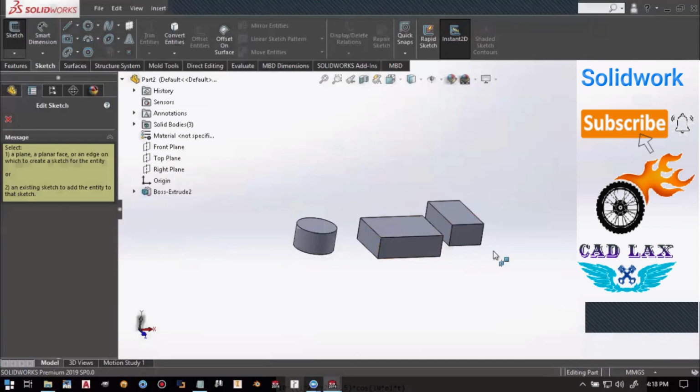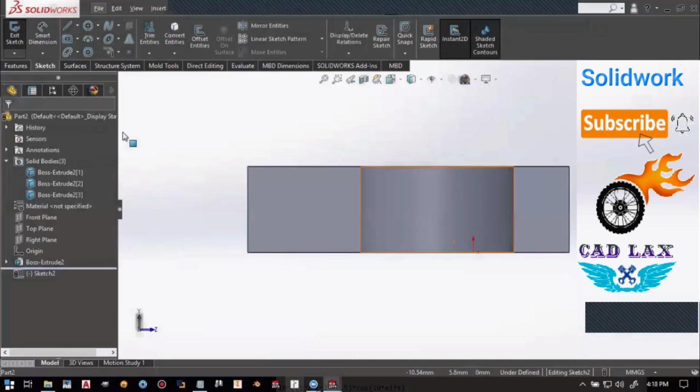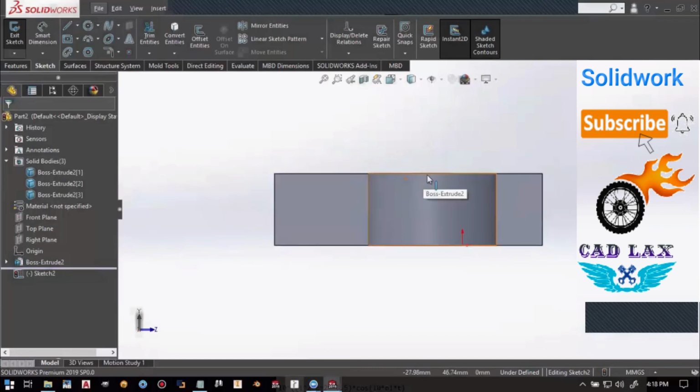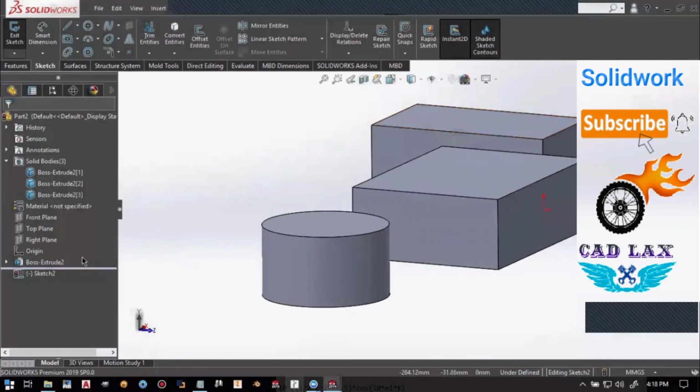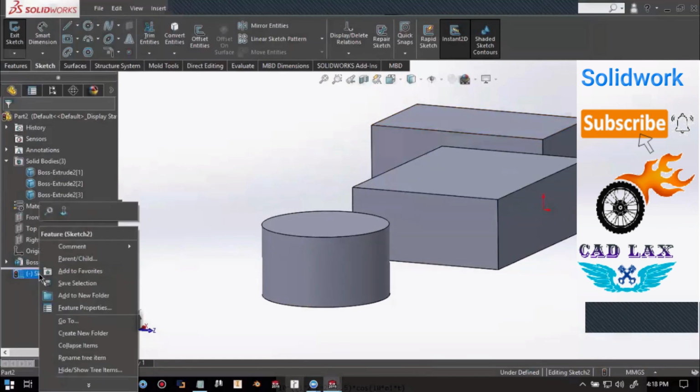I can create a sketch, so I am choosing this one. Now this is automatically rotated normal to the screen. This option is not turned on by default in SolidWorks. You can turn it on. If this option is not turned on in SolidWorks, what you can do to make it normal to the screen is right click on the screen, and here is the option of Normal To.